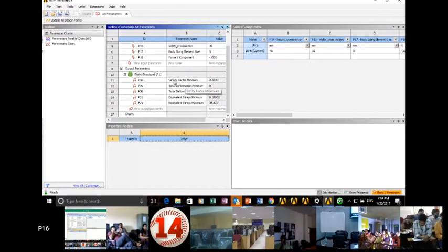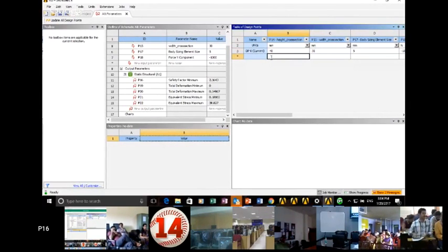For the time being we won't consider this factor of safety, as I'm going to explain it to you using response surface. Now we'll consider only total deformation, maximum and minimum value, and equivalent stresses, maximum and minimum value. So now I'll simply set various design points. For example, I increase the size from 40 to 45, and the width of the cross section also I change.